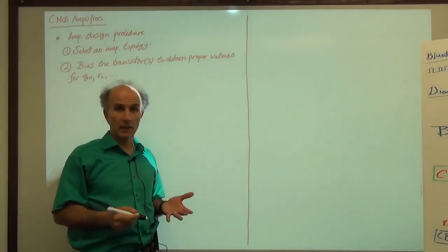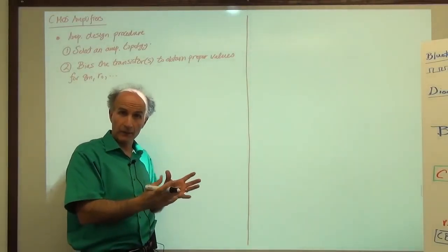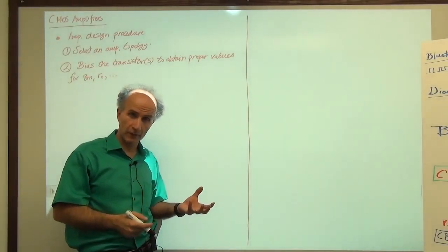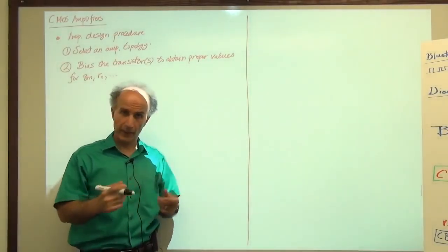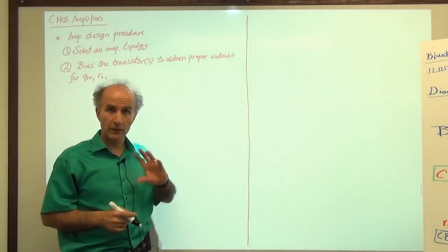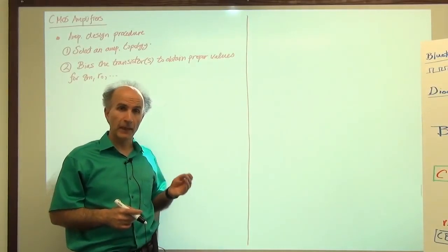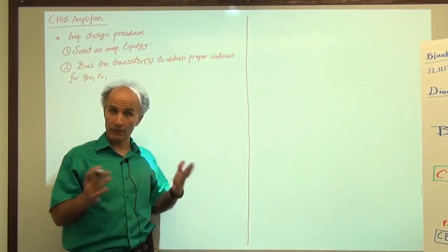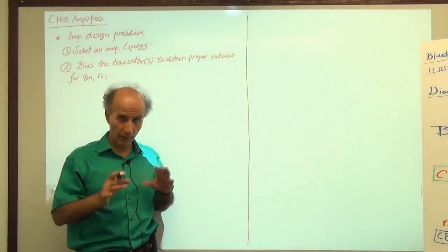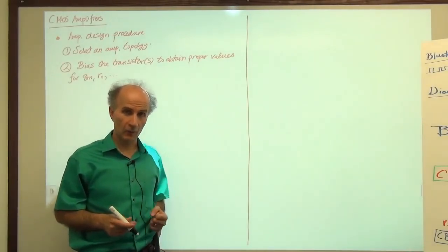As we will see, the overall characteristics of amplifiers heavily depend on the small signal properties of the transistors, whether we have a high GM or low GM, high RO, low RO, and so on. So for each device, we have to bias it properly. If you remember from our previous examples, if the device has no bias current in it, the device is dead. If there's no amplification, we can't use it. So we do have to bias it up before we hope any amplification will occur.